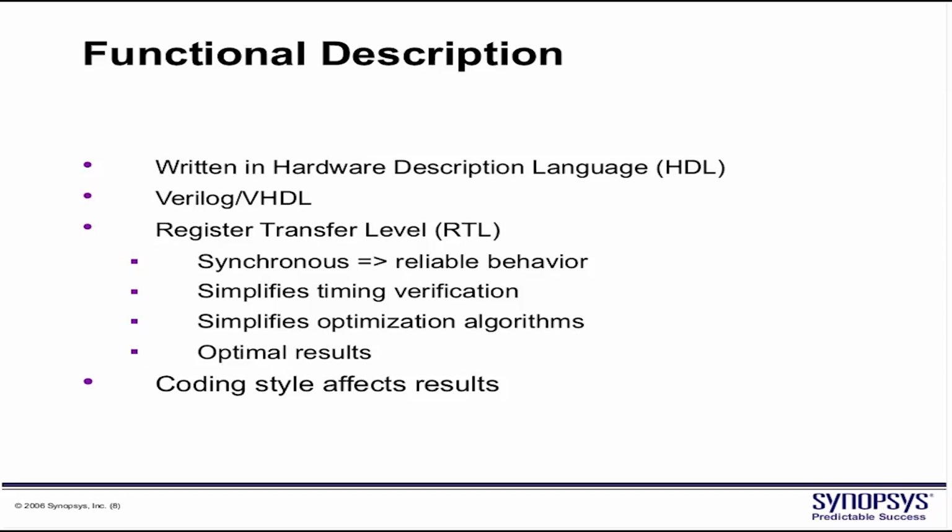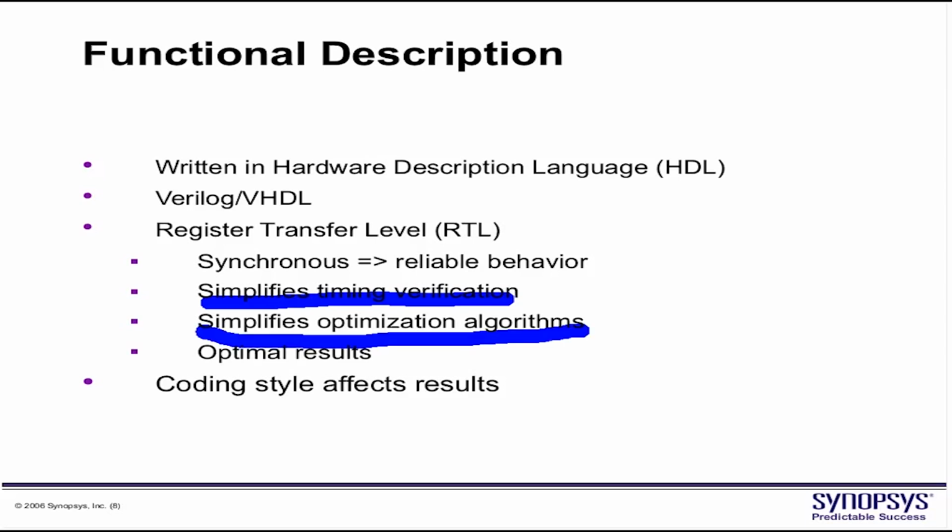The very big advantage of a synchronous design is the reliable behavior. This thing is very important. It simplifies timing verification. We will see that further in Unit 3 and Unit 4. It also simplifies optimization algorithms, which is a derivative of simplified timing verification.